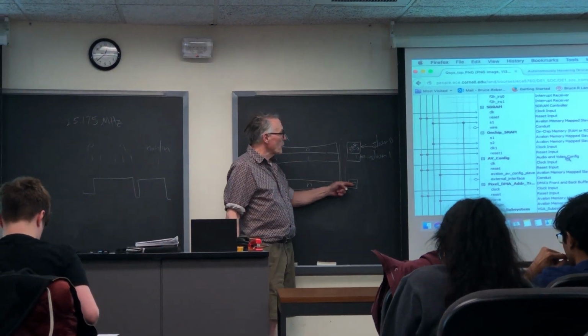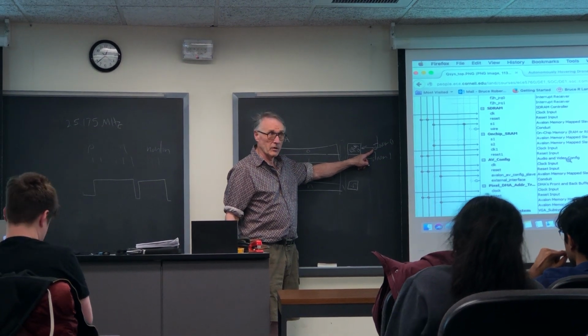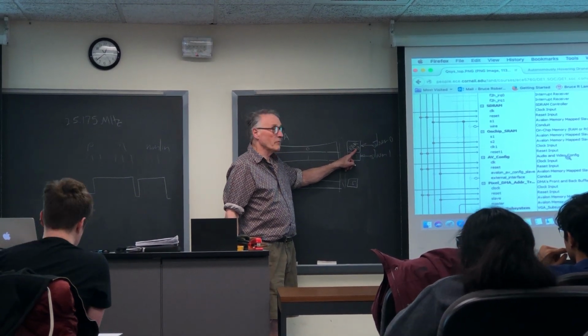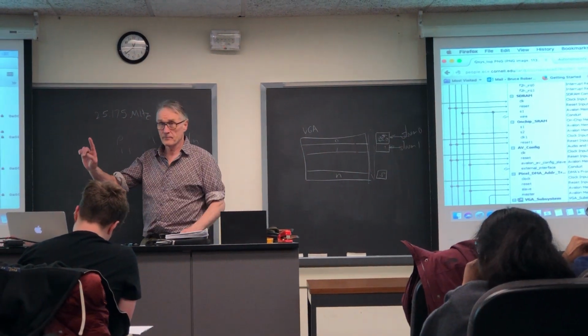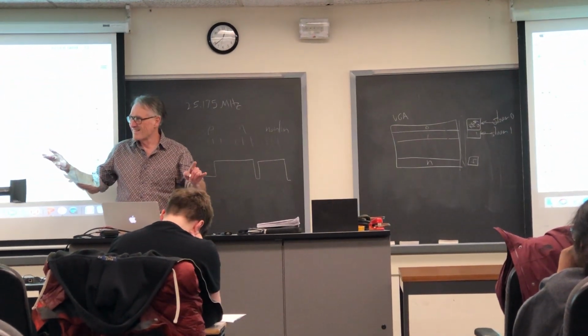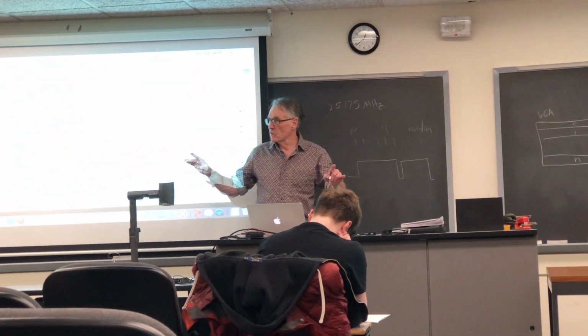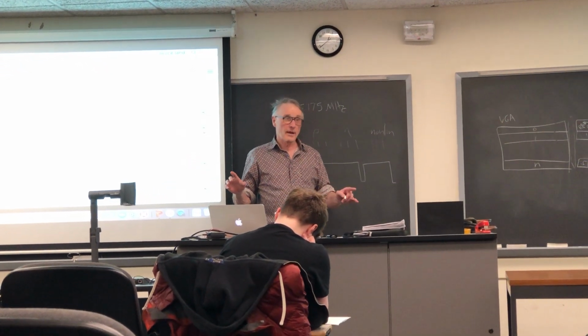Because the memory is dual ported, the solver can still write at all times to the RAM block, even when the VGA is reading from it. So there's no memory contention, either between solvers or from the solver to the VGA. You can't do better than that.